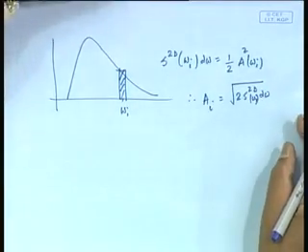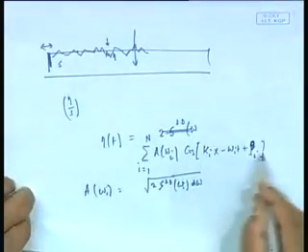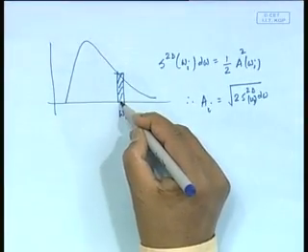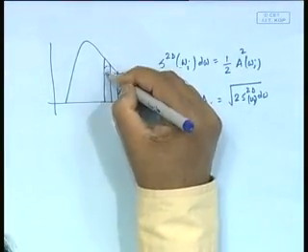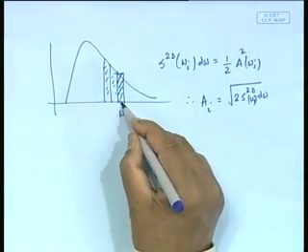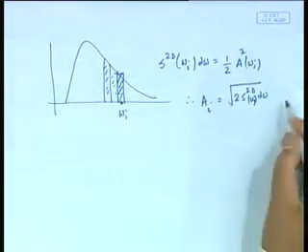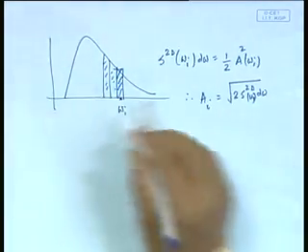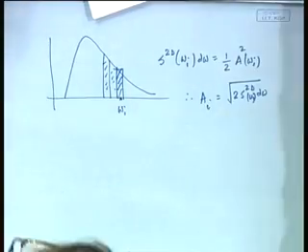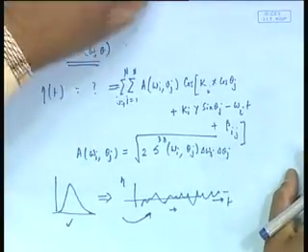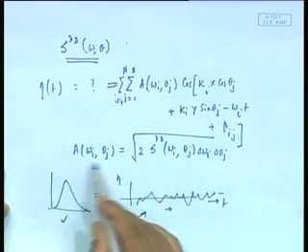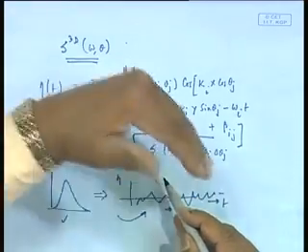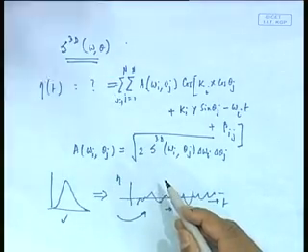So, therefore, I end up getting this eta by summing this all. So, what I mean, I break it down to several parts, for each one I find out what is the amplitude of the wave of this frequency, and add them up with a random phase. Here what I have to do in a 3D case, I have to do the same thing, but I have to do a larger breaking. I have to break not only over the I axis, but also over the j axis.